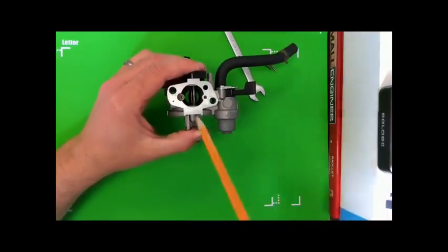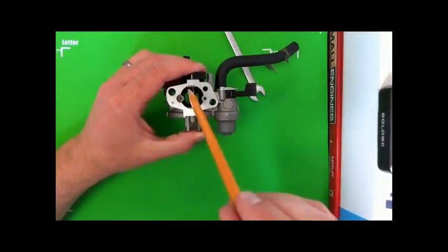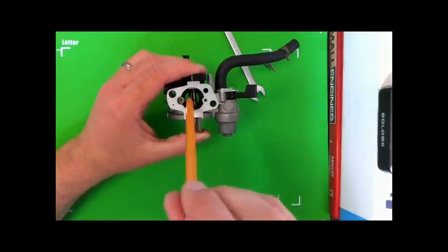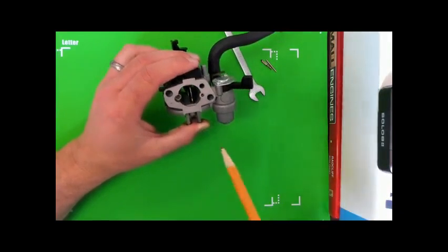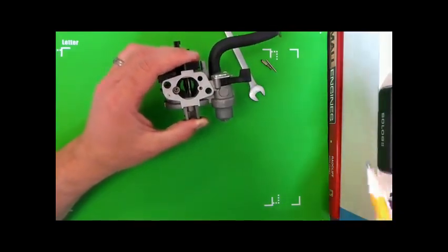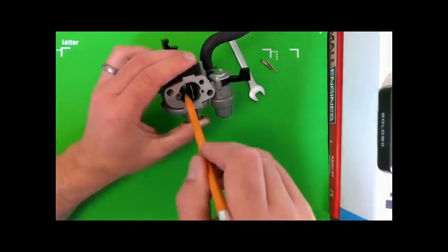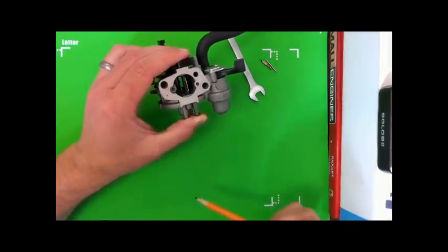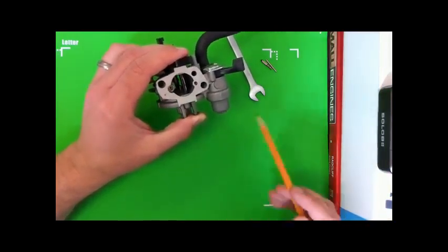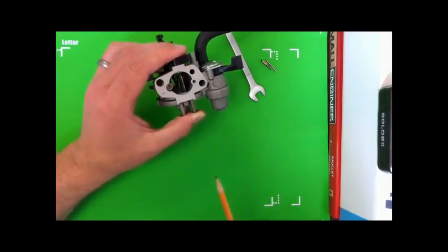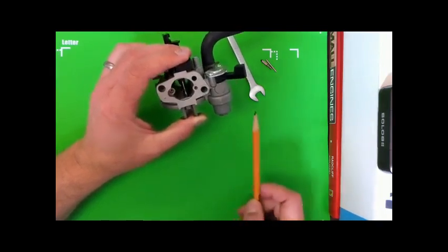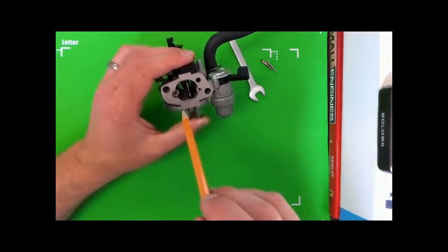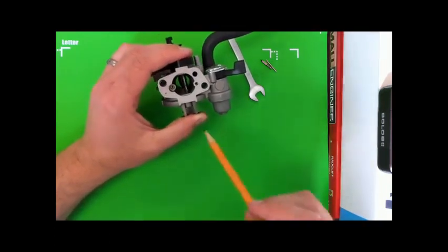Now we look in this barrel of this carburetor, you can see the diameter appears to decrease once we get right in the middle of that carburetor, and it's not that it appears to decrease, it does decrease, and we can see that piece of brass right there sticking up. That's the other end of the main jet I referenced earlier. That's where most of the fuel is going to be pushed or pulled up into the carburetor for vaporization. And that narrowing of diameter is called the venturi.